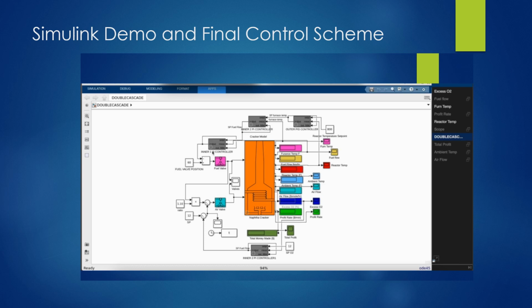The set point for the fuel valve is set at 60% open, a decision aimed at maximizing daily profit. Additionally, a ratio controller plays a crucial role by linking the airflow rate to the fuel flow rate. This ensures the process operates safely, maintaining excess oxygen levels above 9%.